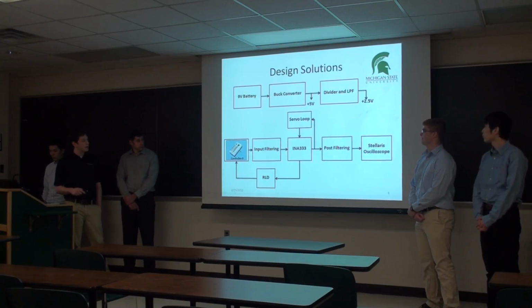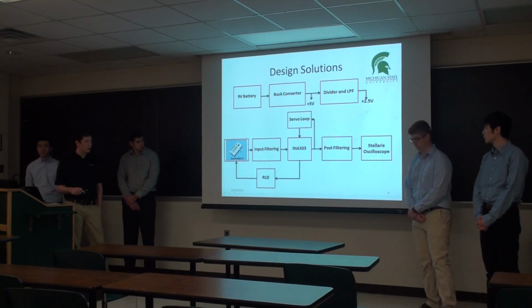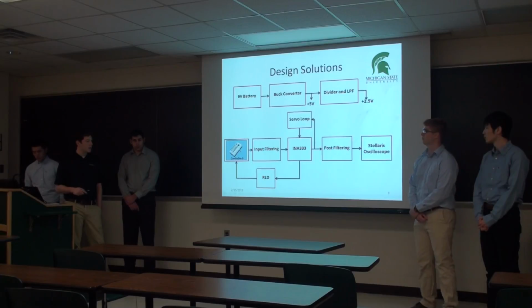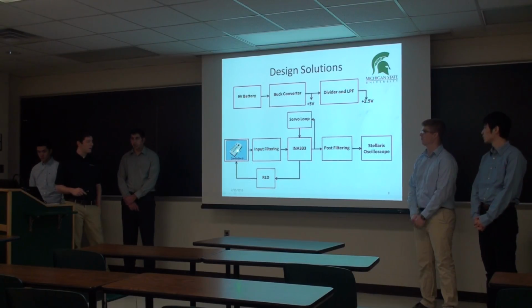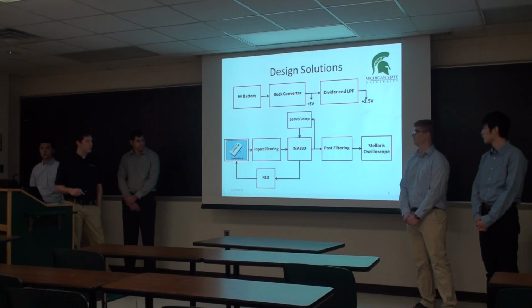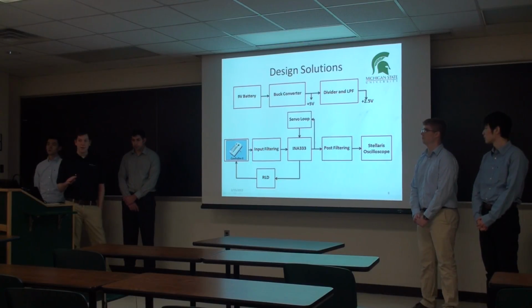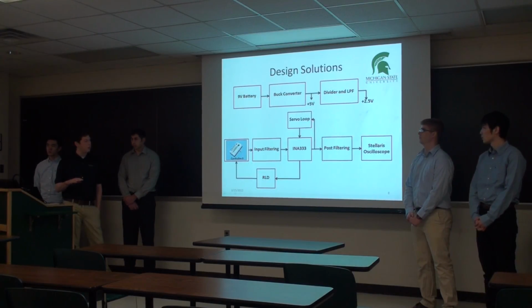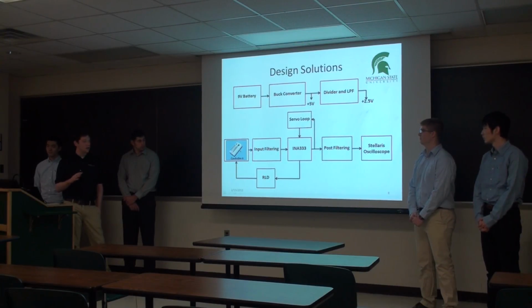As for our ECG circuit, we have either the CardioSim or, later when we get the finger sensors, an actual ECG from anyone who walks up to the demo board and puts their fingers on it. We go into some input filtering, which is an RC network, to try to get rid of high frequency noise. Anything above the 50 to 60 hertz range we want to get rid of, because of the power coupling that bodies can have at 50 or 60 hertz. The ECG signal is around 2 to 3 hertz, so that's where we're focusing.